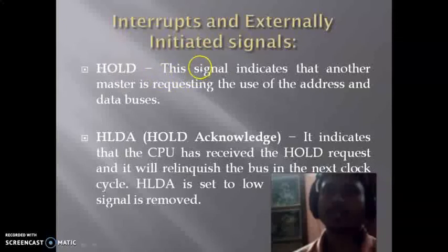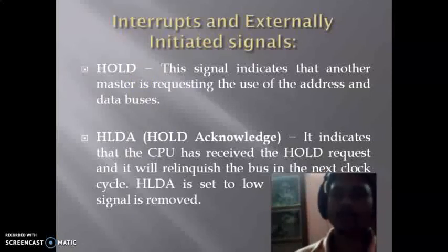If the microprocessor is performing any task, it will complete that task. After that, the hold request will be accepted, and the microprocessor will send a HLDA, that is a hold acknowledgement signal, to the peripheral device, telling it that the microprocessor accepted the hold request. So this is the operation of HOLD and HLDA. These are the externally initiated signals.